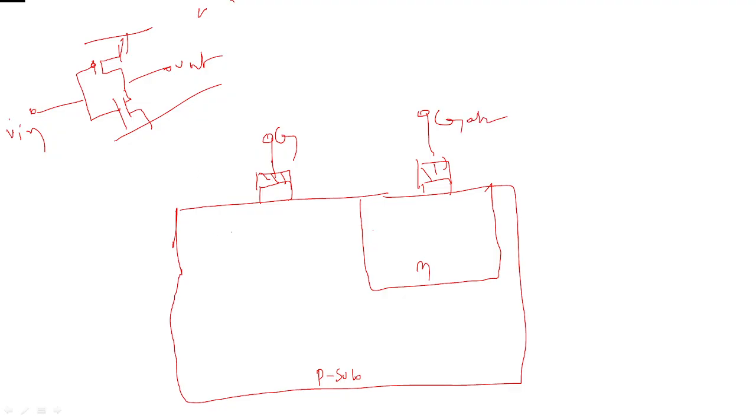To design the left side transistor, we diffuse the electrons because it is already a holes material. So by heating this material we insert electrons, and that is named the source, and this is named the drain. Similarly here, to design the source and drain terminals, we diffuse the holes. This is also a source, and this is the drain terminal. This can be used as a CMOS inverter. This is the fabrication process to design a gate terminal.